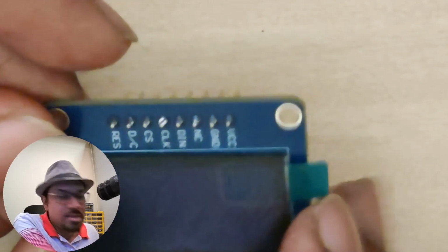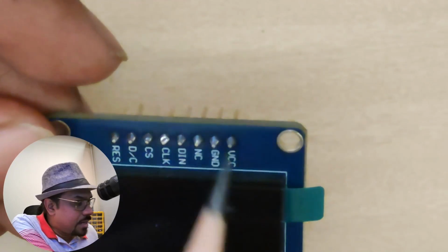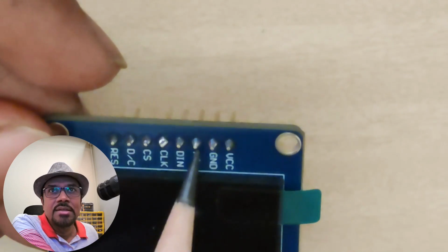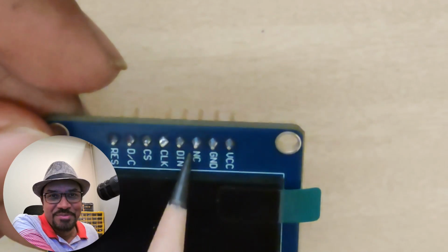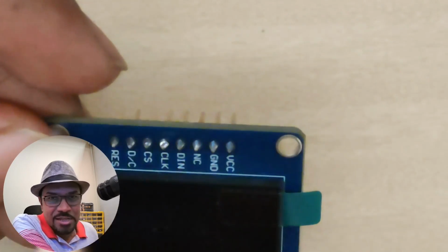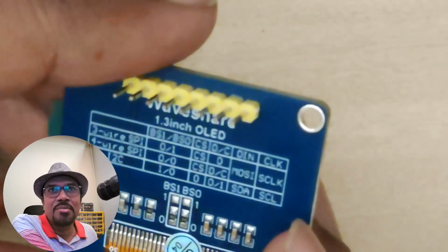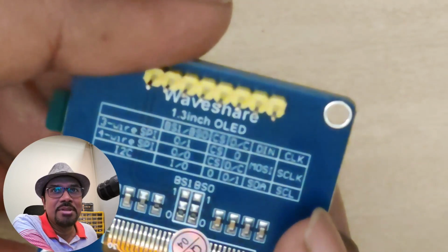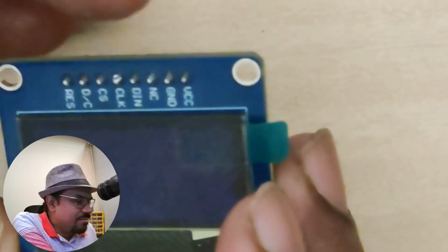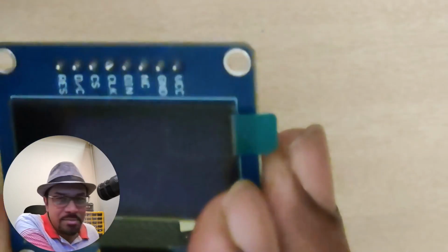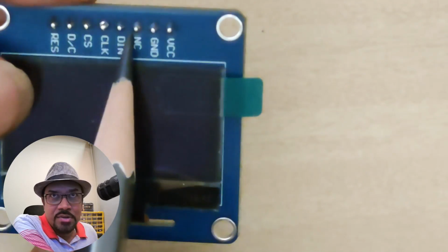This is a Waveshare board, 1.3-inch, and you can see it's got 8 pins. Though there are 8 pins, you should note that there's a VCC here, ground. This pin, NC, stands for no connection. You don't connect it to anything on your Raspberry Pi Pico. And why is this pin exposed? I have no idea. To be honest, I don't know if there's anything marked about the NC pin. No, nothing on the table. Maybe for the purpose of symmetry, or for compatibility with certain boards, perhaps. So normally you don't connect it, and you just need to ignore this NC pin.